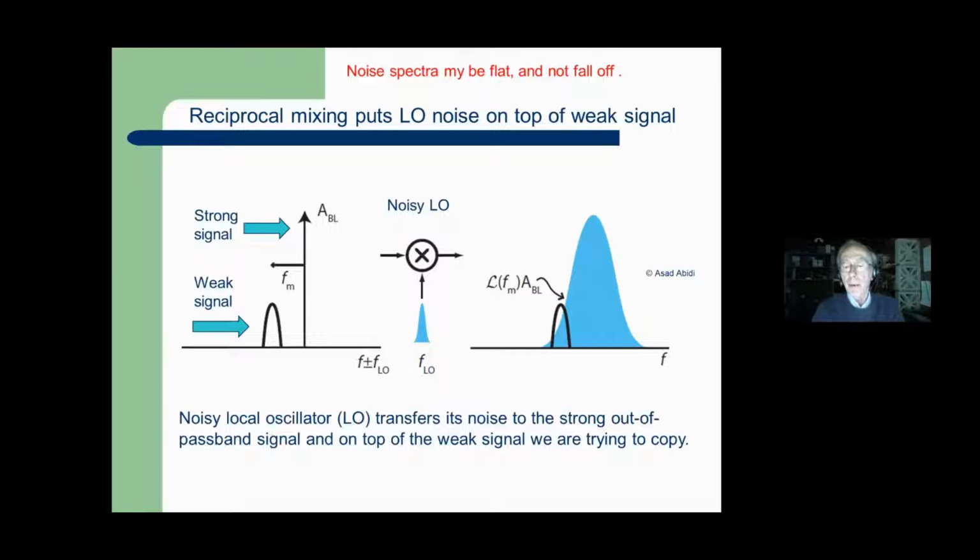Now this little graphic assumes that the phase noise of our oscillator is going to fall off fairly quickly, and maybe it does, but a lot of radios don't. Matter of fact, some are just as poor at 100 kilohertz or 200 kilohertz or 300 kilohertz. So that area where the strong signal needs to be close to the weak signal may be down the band a lot. So the phase noise was a big problem. We're lucky to say now that's really improved on some of the latest radios.